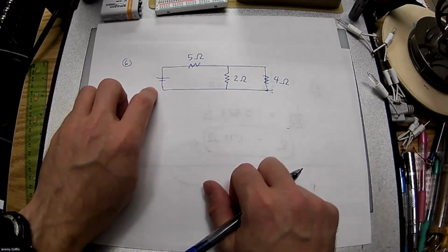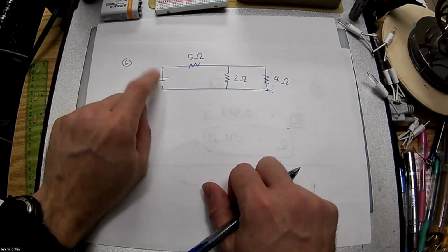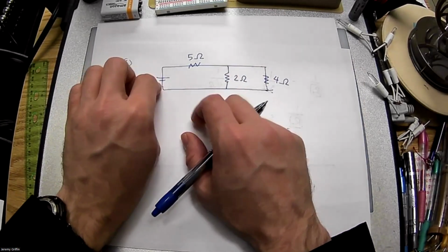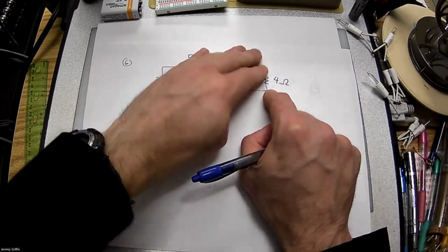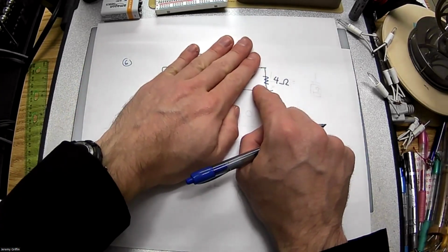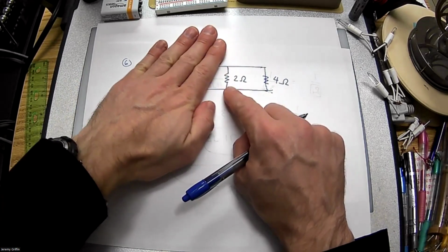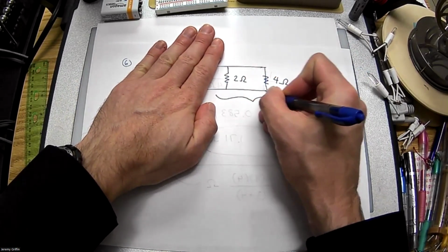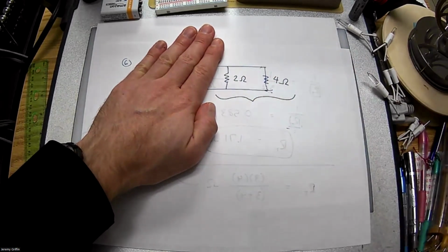So the process I just told you: find your voltage source. I didn't even tell you how many volts it is, but that didn't matter for this question. Fly over to the opposite side. So I'm just going to start with this 4 ohm resistor. Work back towards the voltage source, and then I run into this 2 ohm resistor. Now, next question is, how are these 2 resistors interacting? Is that series or parallel?